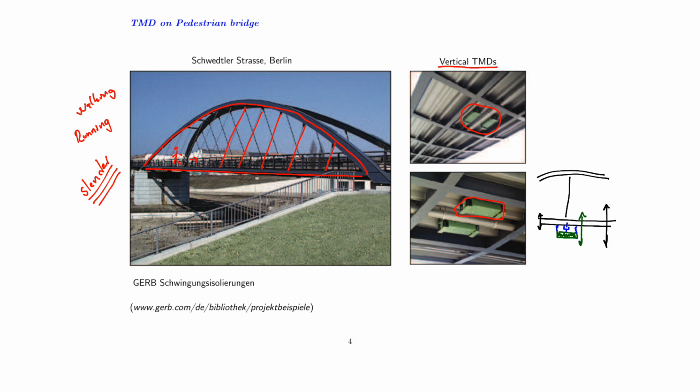So when people are running across the bridge, they will have no problems with comfort, but underneath the bridge, the TMD will vibrate heavily, and of course there should be space enough in here to accommodate these large TMD deflections given by an amplitude. So make sure there's room enough inside your structure or underneath your structure to allow these large TMD amplitudes.